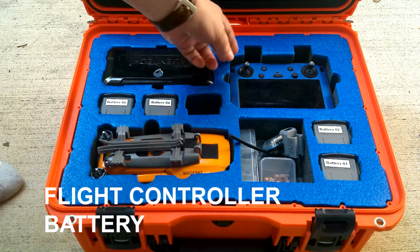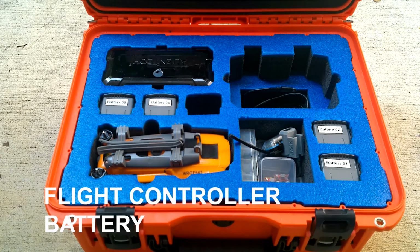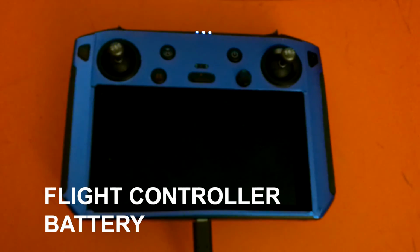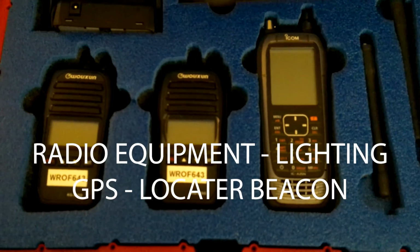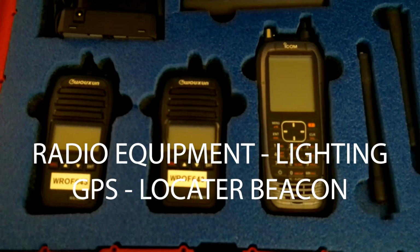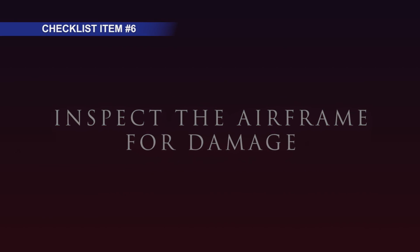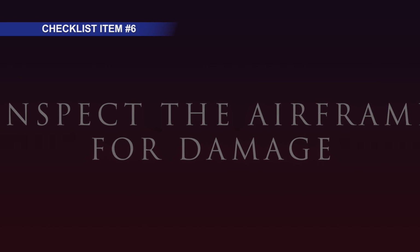The second battery we need to make sure is charged is the drone controller battery. It needs to be fully charged before each use. Other things that you might like to include on your checklist are making sure any radio equipment that you have is fully charged, or any lighting or GPS equipment that you may use. And that brings us to number 6 on our checklist, to inspect the airframe for damage.